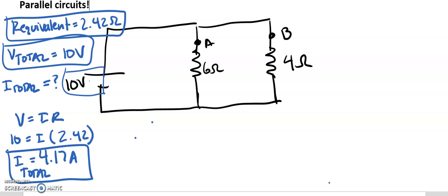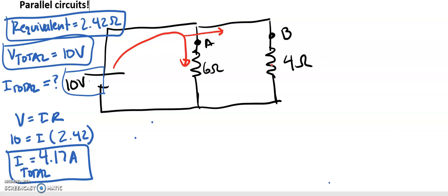So now let's go ahead and think about this. Parallel circuits are slightly different than series. In a parallel circuit, we just talked about the current can split directions. So is the current going to stay the same or change in the circuit? It looks like it's going to change because not the same amount of current, or electron flow, is going to flow down each resistor. While the cool thing about parallel circuits, which is why they're so great for wiring houses or other things, is the voltage will stay constant through each thing.